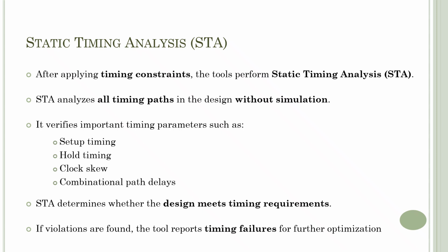Now that we have applied timing constraints to the design, the next step is static timing analysis, commonly known as STA. STA is a technique which is used by the synthesis and implementation tools to verify whether the design meets all the timing requirements. Unlike functional simulation, STA does not simulate the design with input vectors. Instead, it analyzes the timing behavior of the circuit mathematically by examining all possible timing paths.